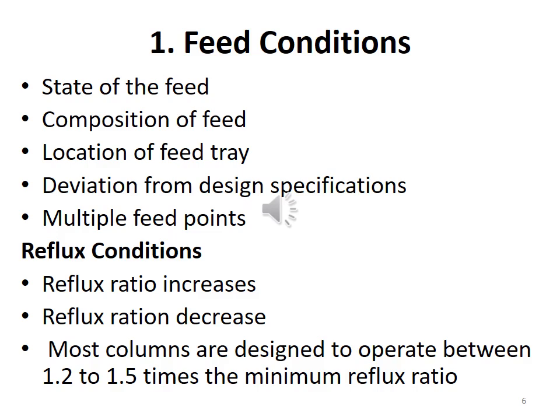And along with this feed condition, separation reflux condition is also very important. As a reflux ratio increases, more and more volatile compounds are being recycled back to the column. So separation becomes better, and thus fewer trays will be needed to achieve the same degree of separation. It means a higher reflux ratio means the lesser number of trays will be